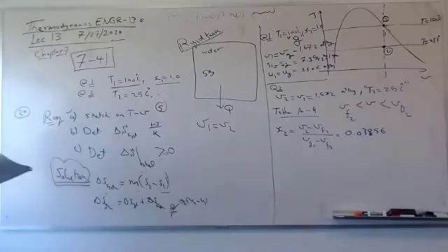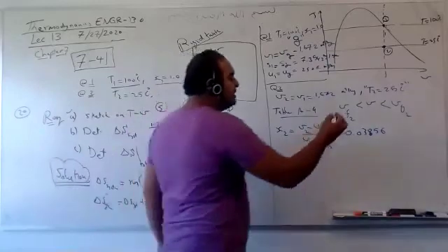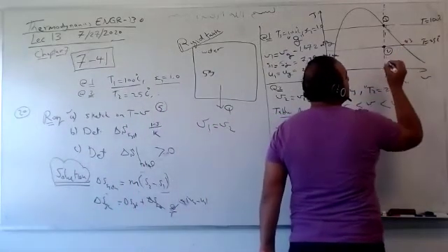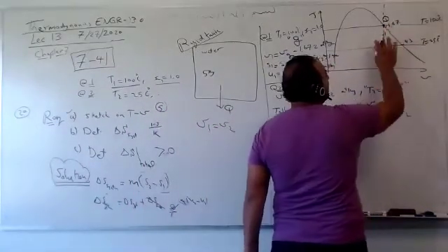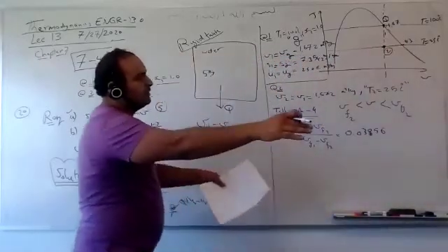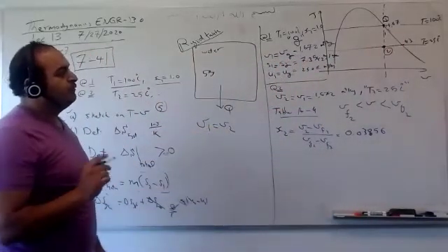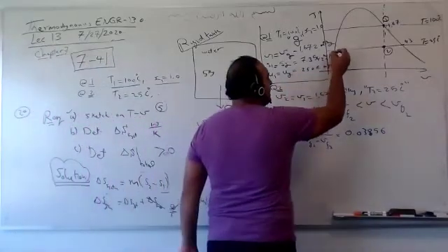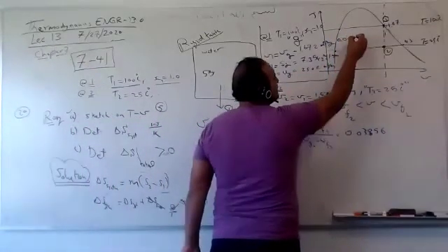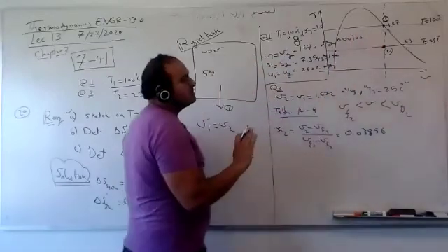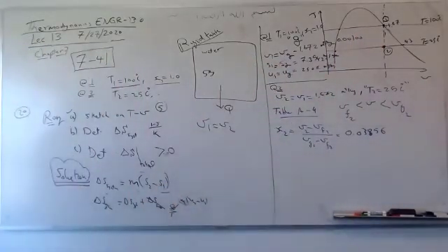It's a huge volume for 1 kilogram because the pressure is so low. So this VG is so big. This one is 1.67, almost 2 meter cube for every kilogram. This one and this one are almost the same, 0.001 something. There is not much change in the VF at x equals 0. But there is a significant change in the VG.